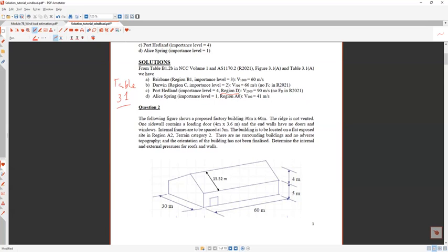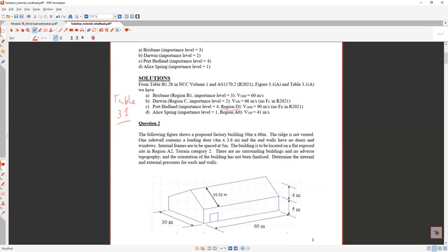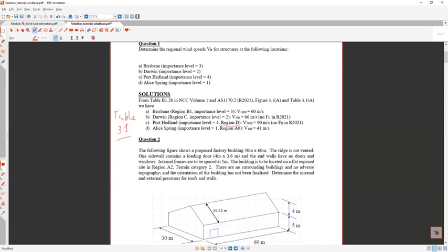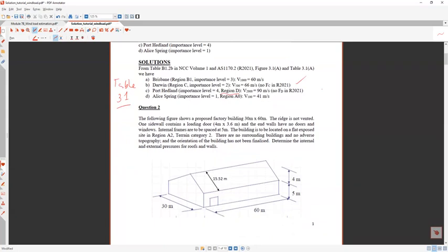So you can see V2000 is 90 meter per second. You have an important structure, which means this is too high a speed, 90 meter per second. Do not think of it as a car speed. Convert that to kilometer per hour and then see what the speed actually is. Because it's meter per second, correlate that, what that speed actually means. Okay, tell me during the break. So Darwin is, again, C. You see, these are all cyclonic zones, C, Darwin. So these are the things to look for, and then we will move on to actual problems.